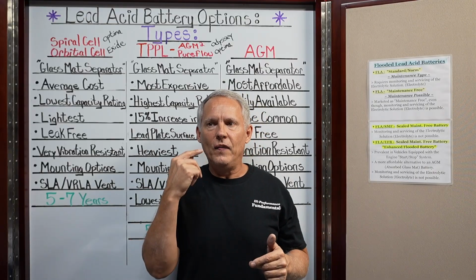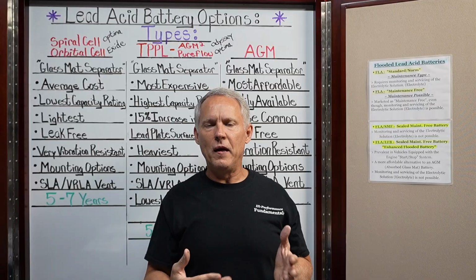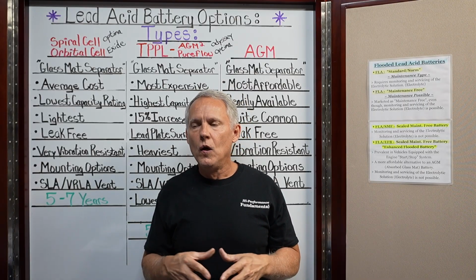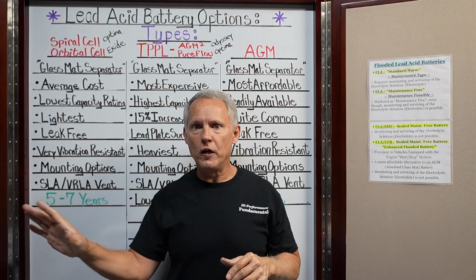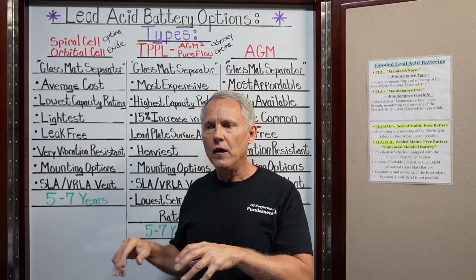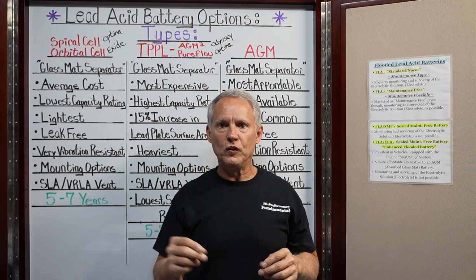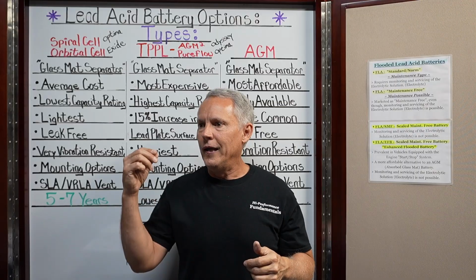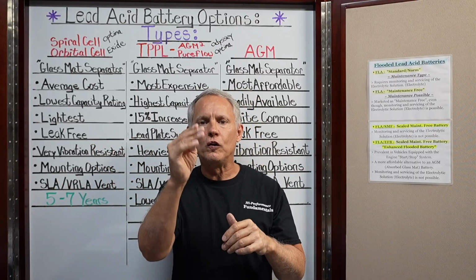So in that realm, in my personal opinion, a 16 volt battery is made for performance cars only, race car applications only, where you are charging the battery externally, no alternator, no generator, or you're regulating it to a point where, let's say your cutoff voltage for your injector drivers or your ignition coil drivers is 18.5, you never go over 18. You're regulating it. You're on top of it, right?